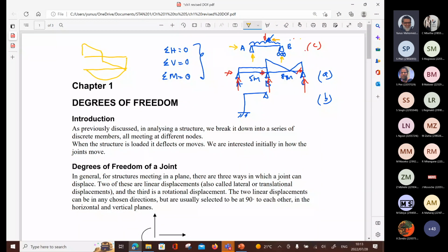But in this case, I'm starting off with a problem: I have three unknowns. It doesn't sound like a real problem because I've got three equations, but when you look at it, I have nothing horizontally and it's not giving me anything. If I take sigma H equal to 0, there's no horizontal external load, then I have the horizontal reactions at A, B and C. Common sense tells me that they don't exist, so I'll just disregard that.